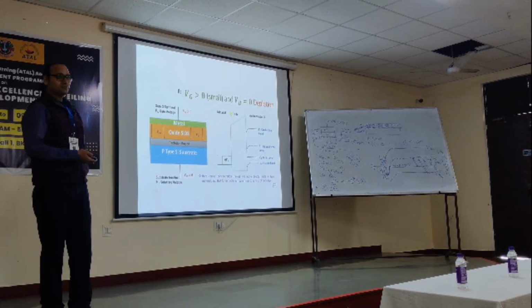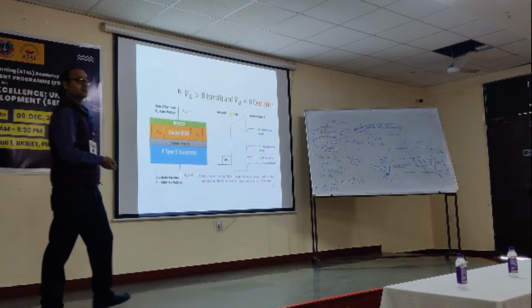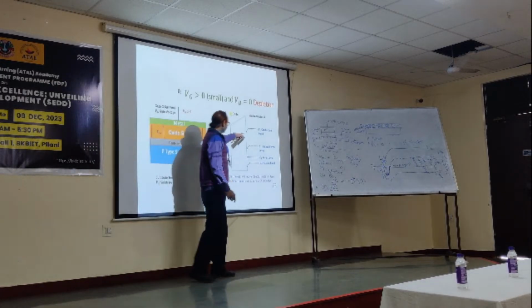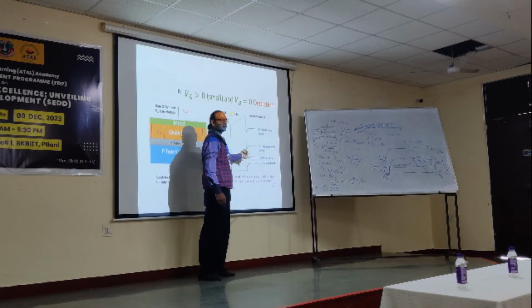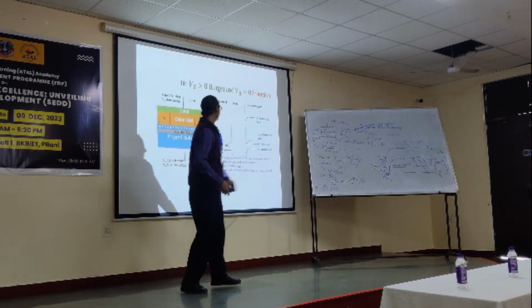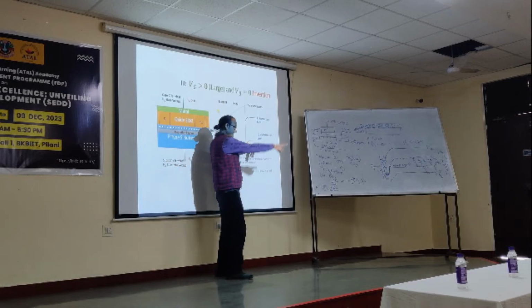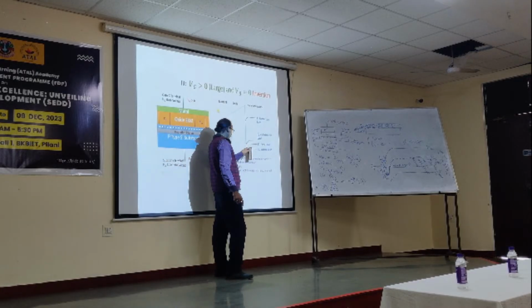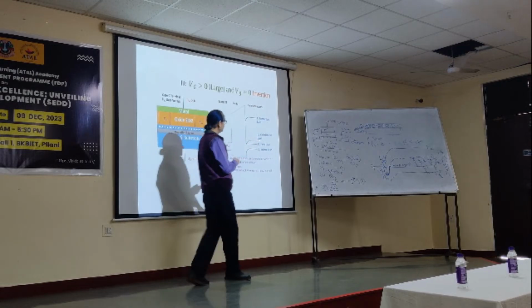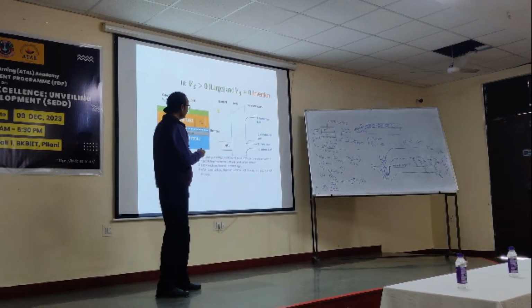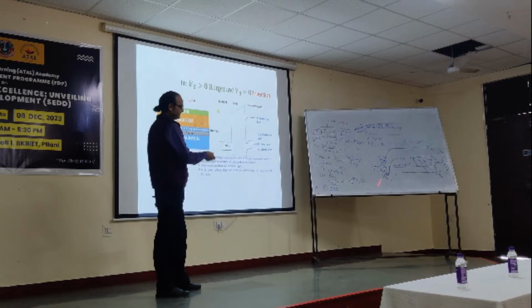So where will be the band bending? Now see, the conduction band is approaching the Fermi level because we have to invert it simply. And here you can say that, as I explained there, now EI will come below EF. You can verify it from here.